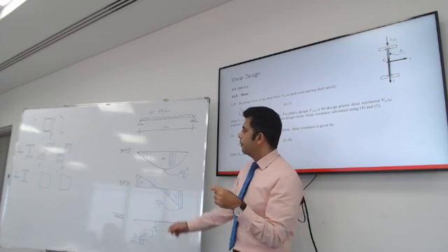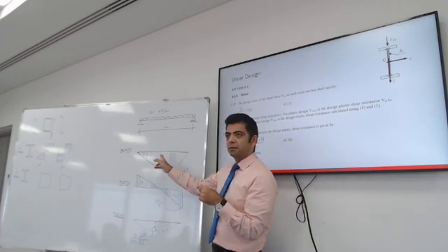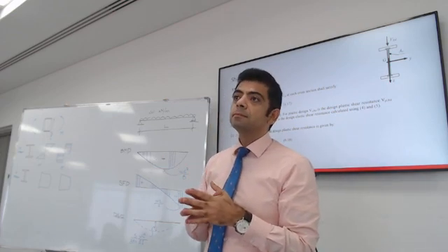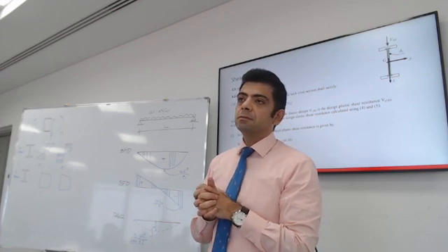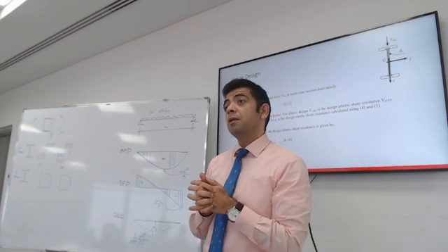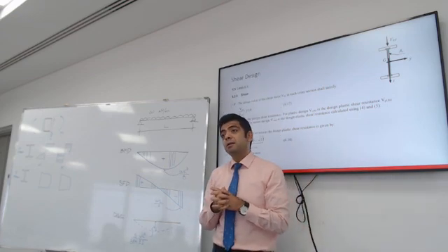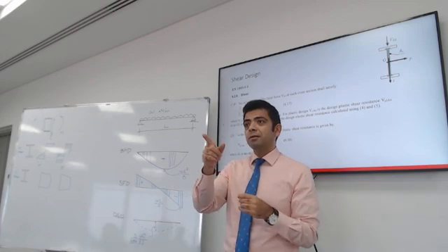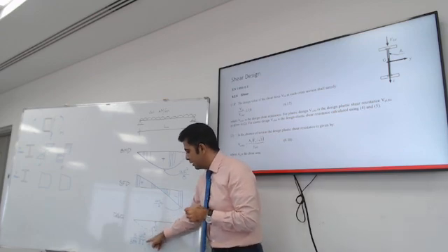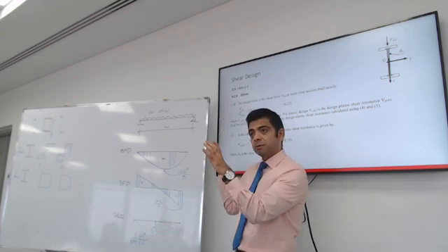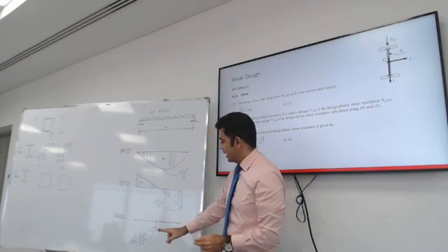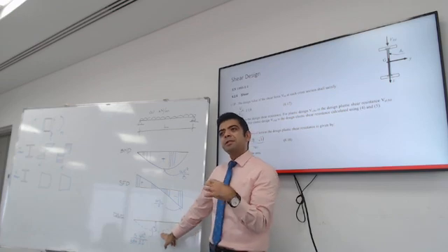We started with the bending design. Now we have the bending design and the shear force values. We take the values and select from a table, the same thing we did last year. So you chose a section. Remember, you chose a beam that has a moment of inertia that you got from the commercial tables. So you need to check that it's not going to deflect too much. So it's a check.